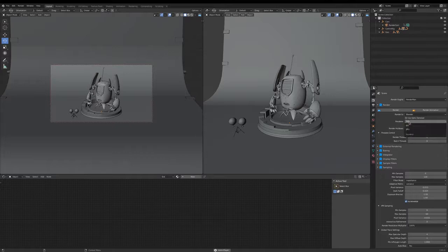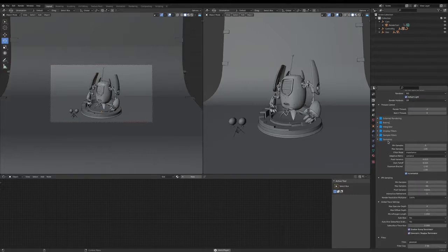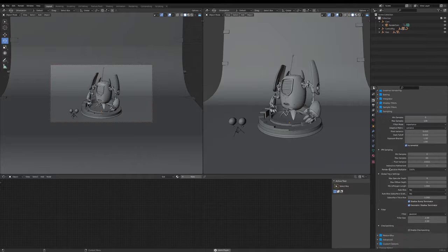And so this next one here shows me whether I want to render with RIS, or whether I want to use the new GPU and CPU hybrid renderer called XPU. And again, we'll have a quick look at that in a minute. And then there's a whole bunch of other options here, but under the sampling here, this is where you define the quality of your renders. You have two separate sections. This first section here defines your final render image quality, and then this second IPR sampling here defines the minimum and max samples and pixel variance which the interactive IPR sessions run within.